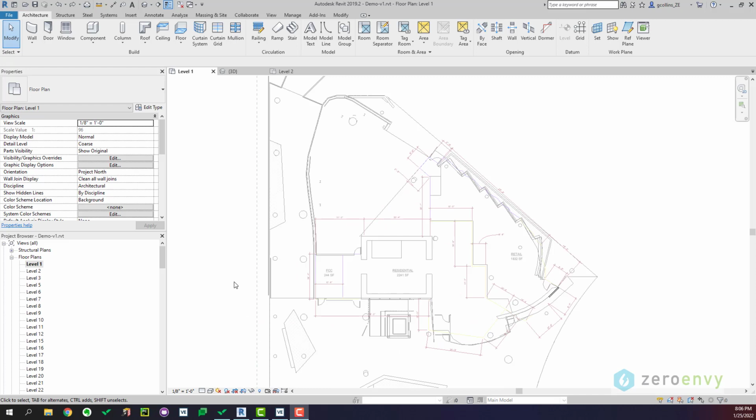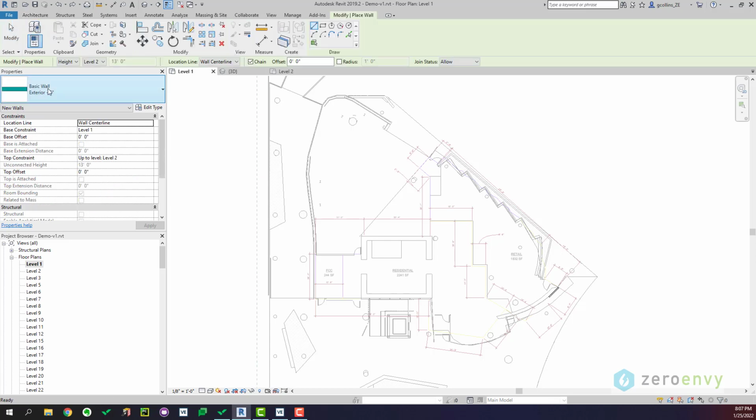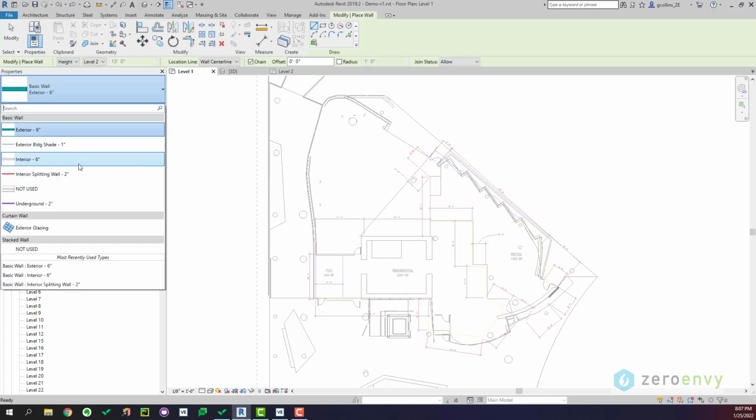All right, so the next step is to create external walls. One thing I forgot to mention is that we have a Revit template in which we have created a bunch of envelope components. Every time we start a new model, we will start from the template and turn that into a project. And then we can just pick the components from there and start creating the model. If you go to wall category, you can see we have created a few wall types here, and we have also color coded them so they can stand out once you turn the color on.